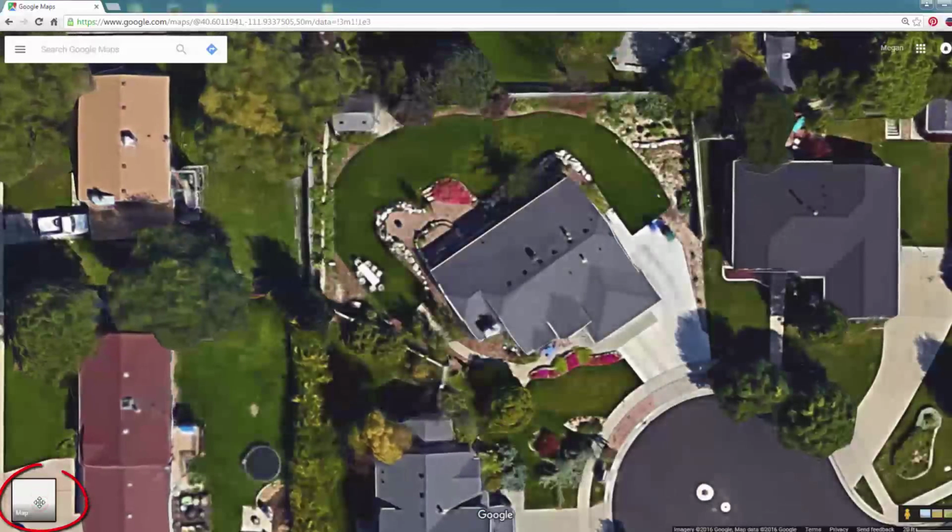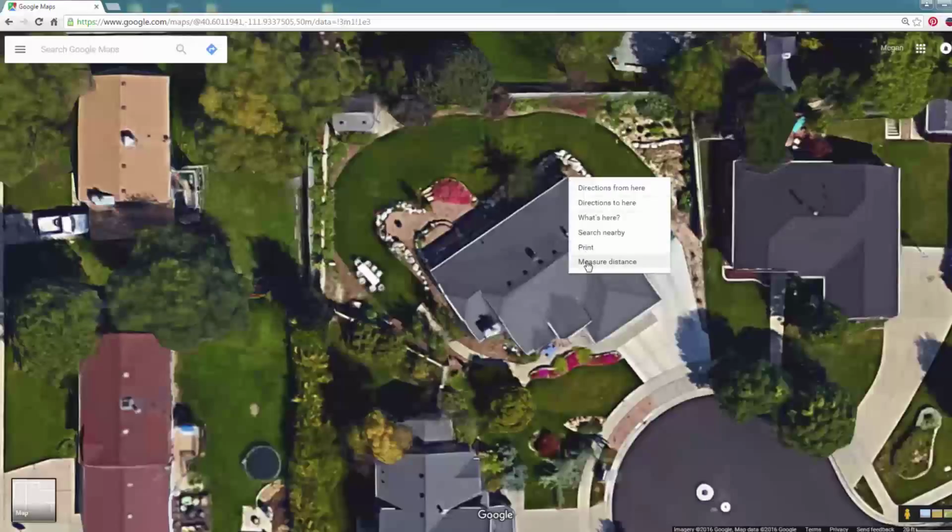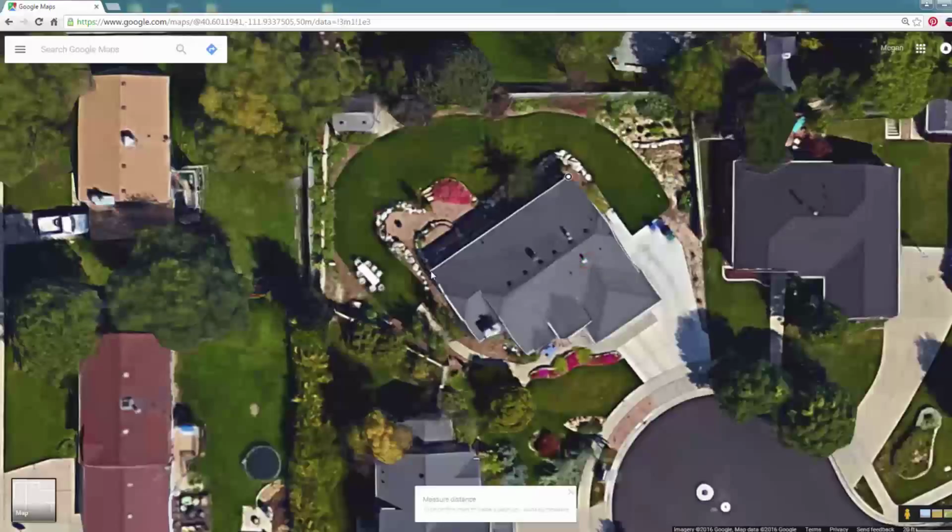We'll switch over to Earth view, and as you can see, this house already has a pretty nice yard. So now we can measure the house. Do the whole right click thing again, measure distance to that corner, 53.95, and you would go around the entire house measuring the house until you felt comfortable that you had that laid out. Then, to figure out how we're sitting in the side yard here, you've got to measure to an exact point.